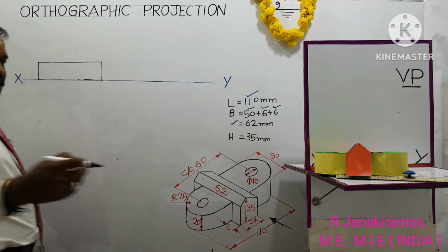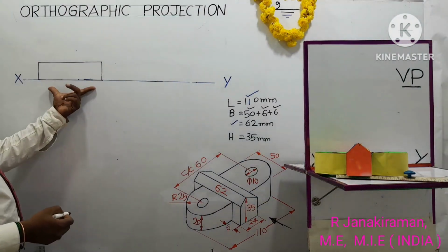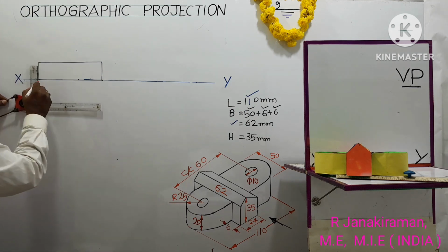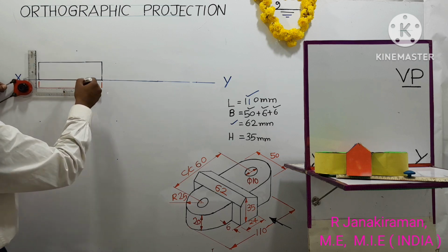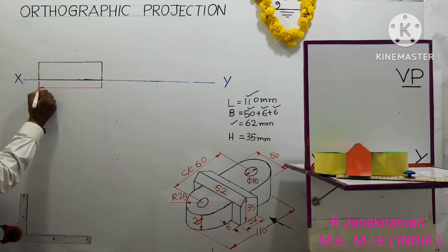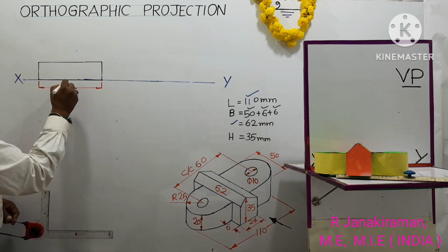In that, the center red color portion is available. So this distance is 110 mm. So let us dimension this. Draw extension lines. Draw the dimension line parallel to the base edge. Provide two narrow arrowheads on both ends of this dimension line. Write it as 110.